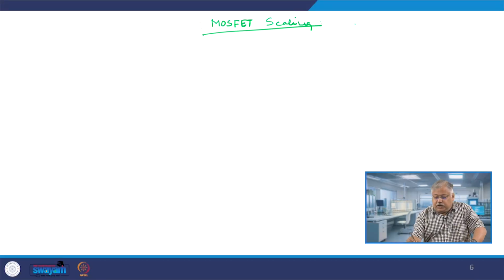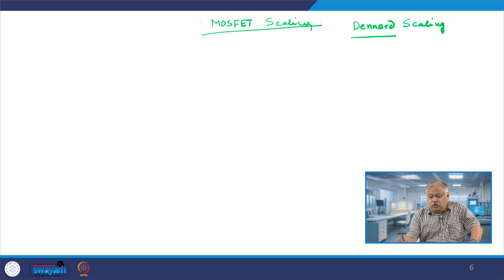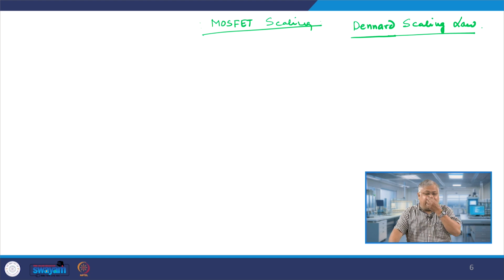Dennard was a scientist who gave a very well-defined set of rules, known as Dennard scaling laws, right. What he said was that if you scale your channel length by a factor of k, what other parameters should change so that you are able to sustain the best performance of the device. This was done by Dennard and it was known as the Dennard scaling law. Now, there are two types of scaling laws available to us.